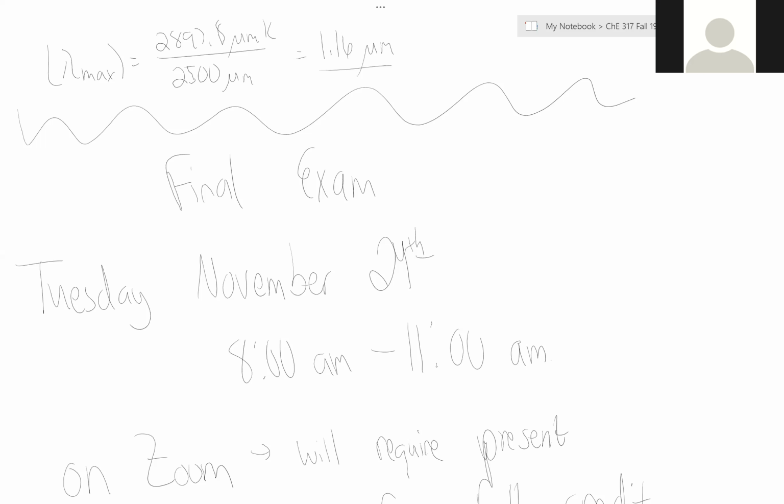Dr. Lopez, I have a specific question about constant values. On the last homework, you gave us a baffle cut, and then I couldn't figure out how to find S sub B, so you told it to me in your office hours, but where should we go to find an S sub B from a baffle cut? I will have to give that to you because it's a manufacturer specified value. It really depends on the type of exchanger and the design of it.